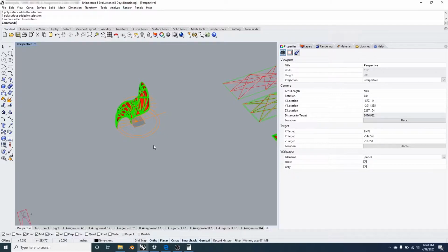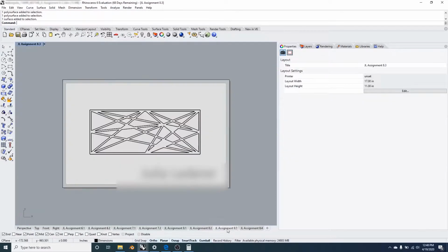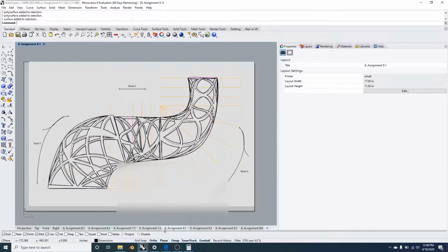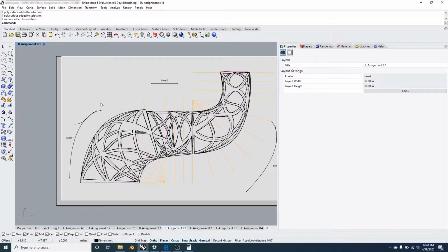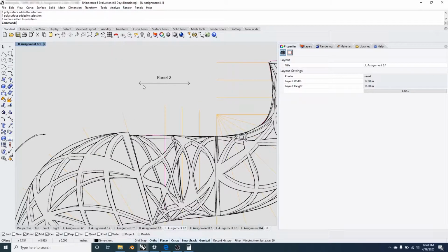So that's one question. The other question was in regards to when we are doing annotations and lines. The question was, how do we make a line or a leader with two arrows? And the answer is you can't do a leader with two arrows because leaders are just for pointing out notes. But you can do an arrow head on a line in two places.